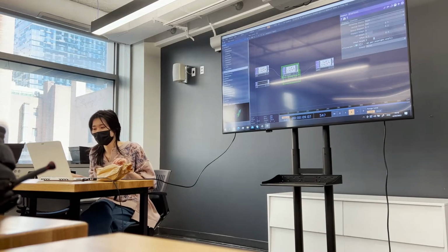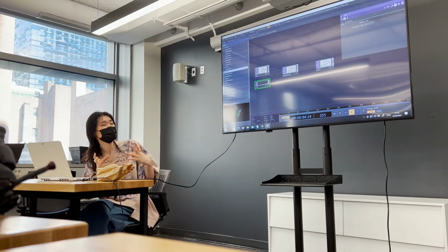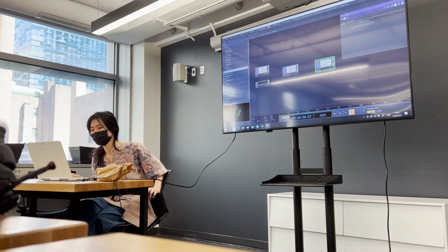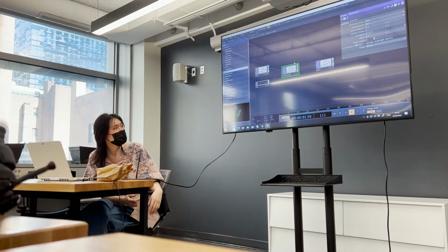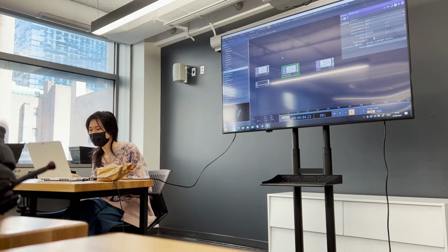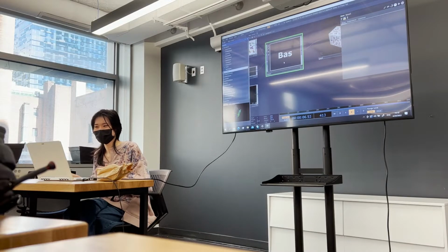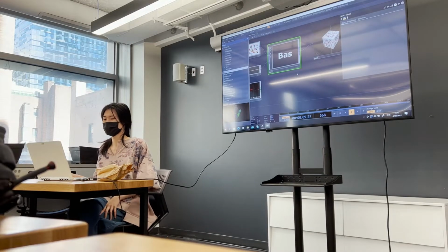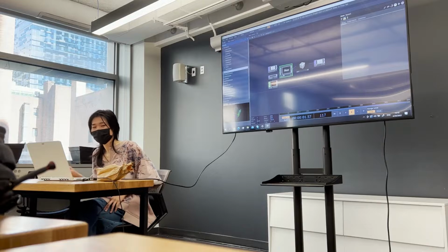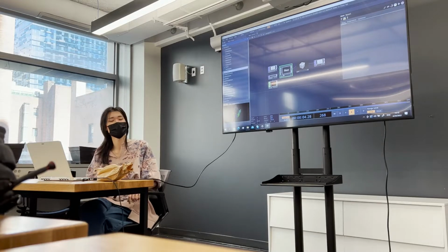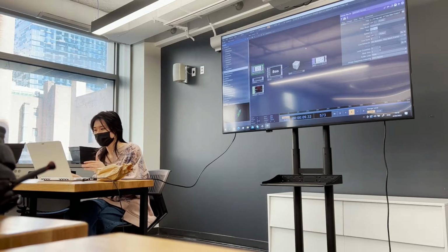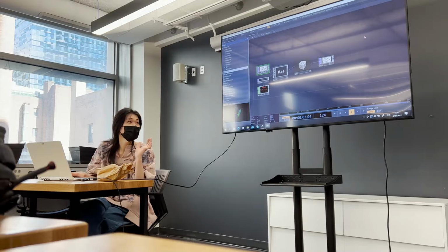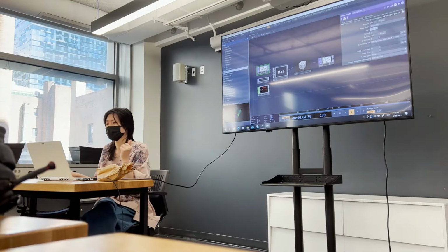You see there are inputs, which are the inputs that go into this base COMP, and also output, which is the output that will go out of this base COMP. You can see this is the node we collapsed before. And if you want to get out of the COMP, you can just scroll out. So yeah, this is the basic interface for TouchDesigner. After you click on one of the operators, you can see all its parameters on the side. You can press P to hide or unhide it. And yeah.